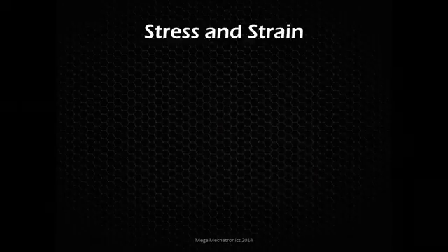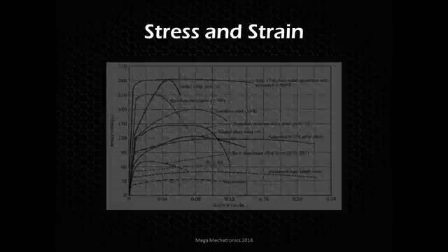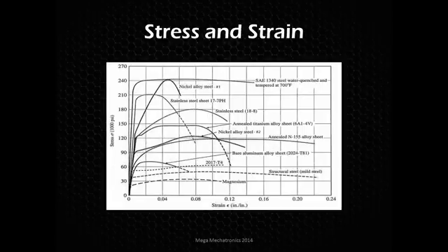And this is what's so good about stress strain curves. We can visually compare materials very easily here because we're using stress, which is standardized load per area, and then strain is a ratio. So we can take data from some other tests and actually overlay it, even if they tested it in a little bit different way. And then various alloys, you can see the steels are up top, stainless, and then we're going down to aluminum, mild steel, and then magnesium right at the bottom there.